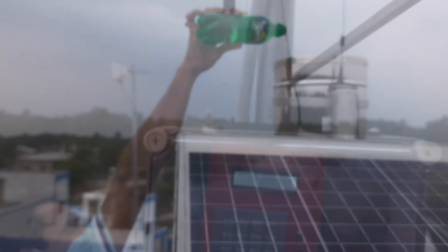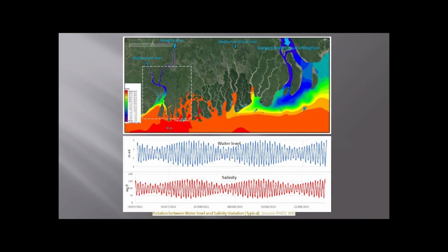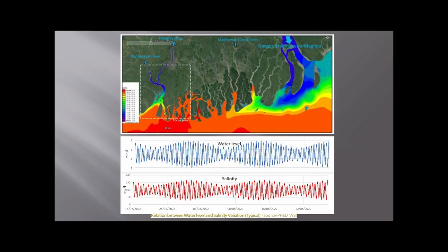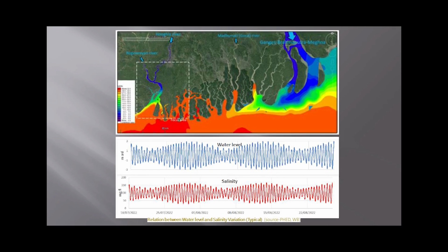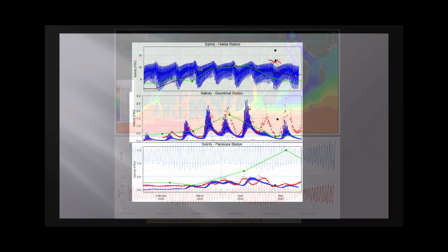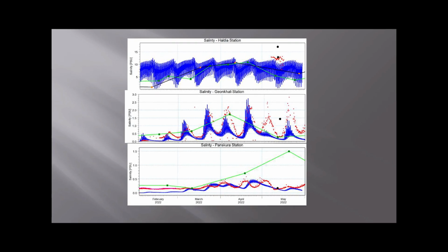Installation of other instruments which are required for appropriate salinity prediction on a wider scale has different levels of challenges and will be discussed in a separate session. In a year, salinity varies monthly, diurnally, and even hourly. The second challenge is to fix how many random samplings need to be taken and for what time period in a year to correlate the instrument data.